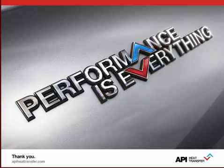All right, thank you. They're coming in fast and furious, so I apologize for throwing these at you so quickly. Can you also provide graphite heat exchangers in a shell and tube configuration? Yes, we can also do the tubes in graphite, so that one side is flowing through the tubes. The tube side can have acid, and the shell side would be cooling water or steam, whatever it is. The design is available in block type, in shell and tube type, and in addition it's also available in plate type. So you can get a complete plate heat exchanger with graphite plates instead of stainless steel or metal plates, generally speaking.